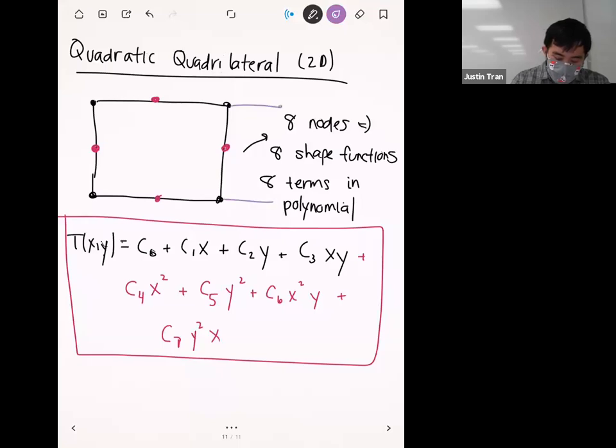These 2 elements share this node right here, right? And so the solution should be consistent at that node. And so what that means is that we shouldn't jump from one element to the other one and have the solution be one thing in one element and then something different in the other one. Okay. So all of these nodal solutions should be consistent throughout the entire mesh. Okay.